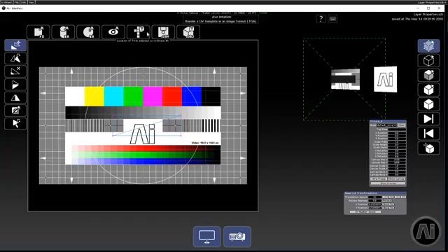The next one along allows us to export a template. So in this case, our template, we'd see this overall area will be our texture, and we'd get this white outline here to show us how it's being applied to this screen surface. And you can use the template to sort of give to other members of your creative team, so that if they're making content, they can know where their pixels need to fall within the screen area to hit certain areas of the target.